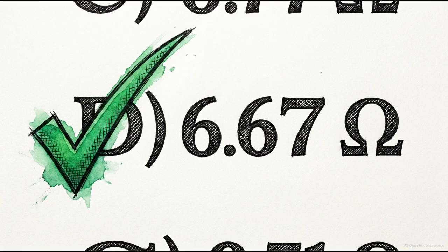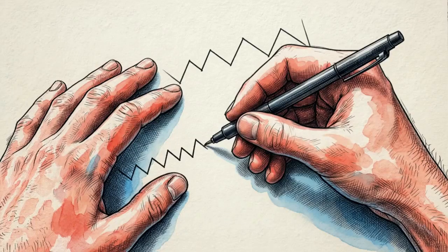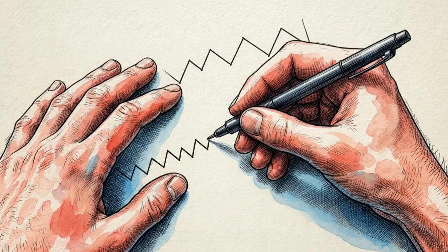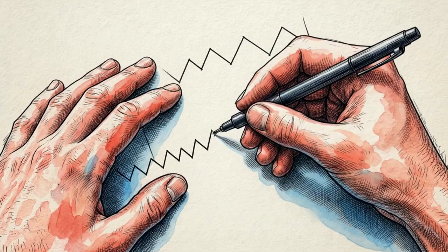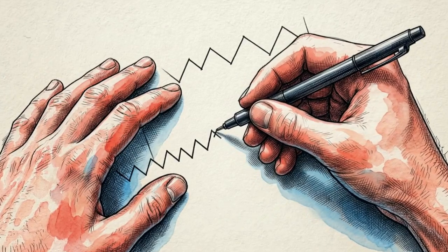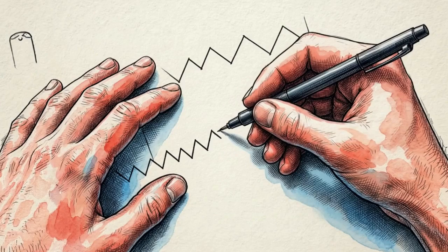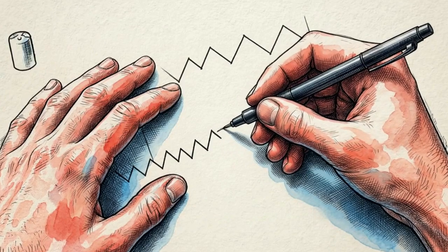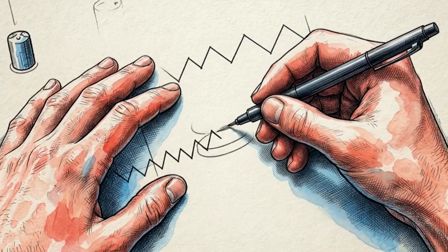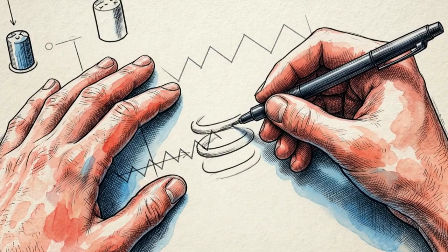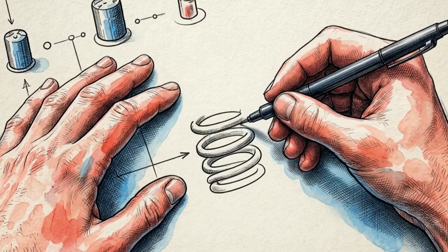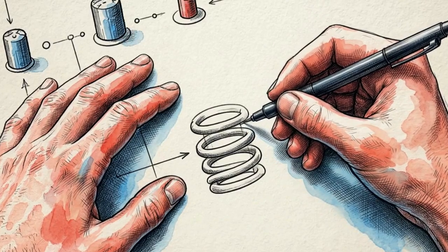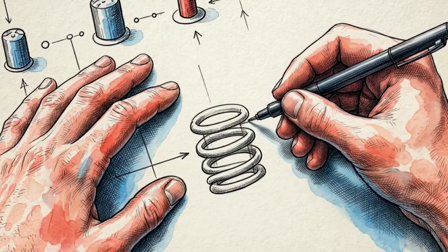Consider a common scenario. A single light bulb burns out, destroying its internal filament. The physical pathway in that top branch breaks. The circuit for the light is open. But because the fan and the socket are on independent branches connected to the main supply nodes, current continues flowing to them without interruption. The independent paths and the uniform voltage of the parallel topology prevent a single failure point from shutting down the rest of the house. This structural fault isolation is why parallel wiring is the absolute standard for domestic engineering.